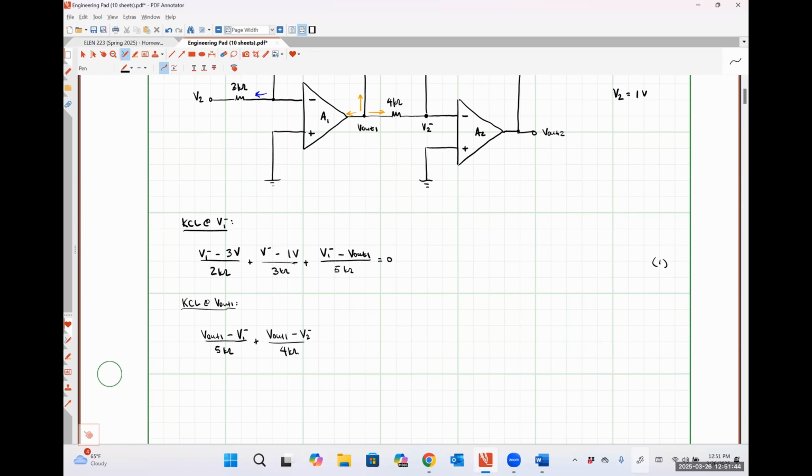Absolutely. So essentially, if we use the practical op-amp model, it would be very easy to see that the current that I have drawn flowing into the output node should be non-zero. But I would need to know what the open loop voltage gain of the op-amp is. I would need to know what the output resistance of the op-amp is, et cetera, okay?